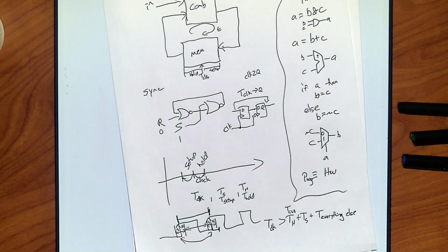There are a few cases where they vary. You might get the signal early, but if somebody drops the input, it might not hold. But you get the data very early on, in which case T hold is longer than T clock to Q. So sometimes you'll do max of T hold or clock to Q, whichever is bigger. In some cases, people measure from when the hold is done, how much longer till your data is available to you. In which case you do T hold plus T clock to Q.